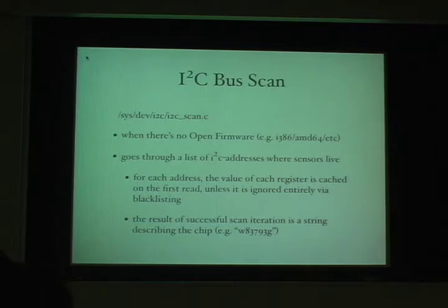The interface of I2C slave devices is the same between all architectures in OpenBSD. Drivers on both Open Firmware architectures and non-Open Firmware architectures match just by string. But on Open Firmware architectures, we use more reliable data from Open Firmware to detect which sensors we have in the system. Whereas on architectures which don't have Open Firmware, we have to look through different sets of registers ourselves and decide which chip resides at that specific address we're looking at.